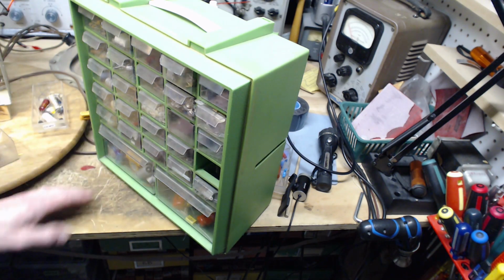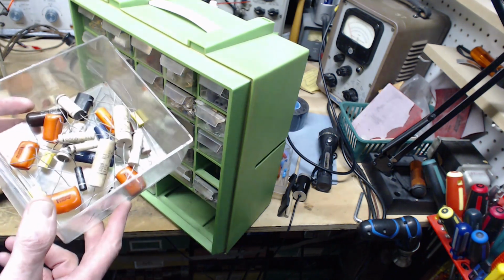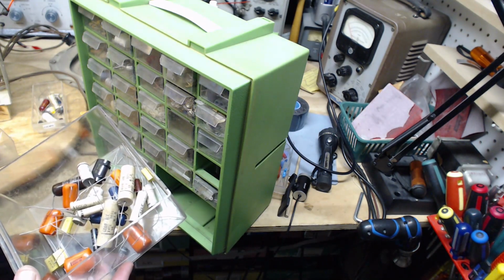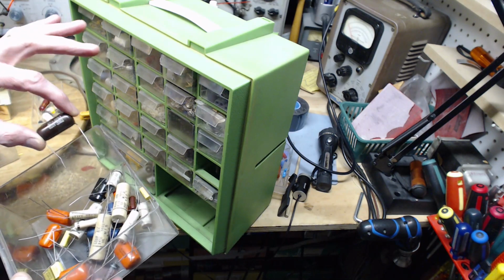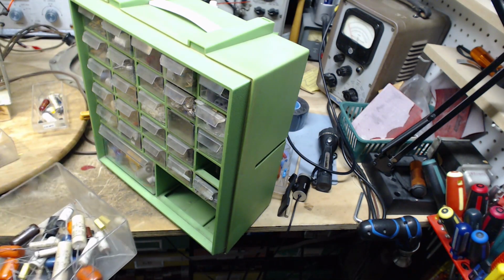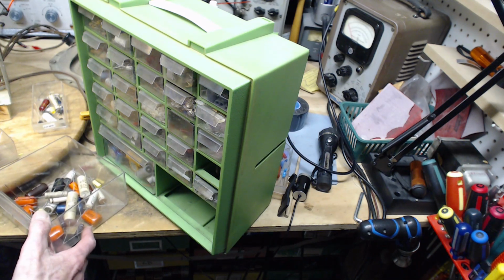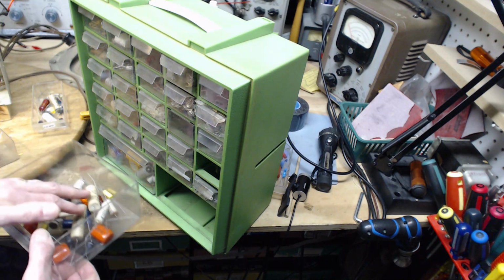I've never looked through this very carefully, although I did know I had a lot of fairly large capacitors in the big bucket here. These are all 200 volt capacitors, and there's stuff in here I could use. Like this one here is basically a 0.5. It's even bigger than the one that was in there. But they're 200 volt capacitors, and the one that came out of the radio is a 300 volt capacitor. And I don't know what the actual voltage is on a screen circuit in this radio, but it's typically 200, 250 volts. So I'm right on the edge of using one of these.